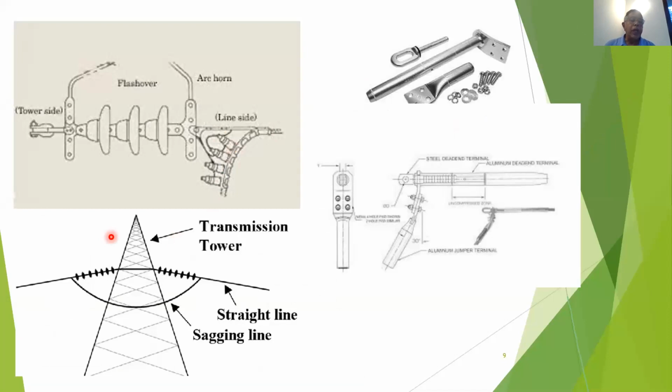And on the other side of the tower, similarly, the conductor comes over here, and both conductors are at a midpoint connected with a parallel groove clamp.